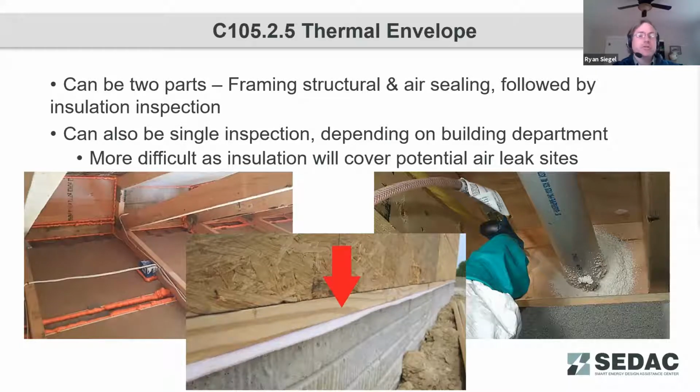that is one opportunity you may have, if you choose to do a blower door test: to do this as early as you can, just to do that verification of the envelope. We go through and verify all kinds of other systems in our buildings, from the fire alarm system to the sprinkler system, many different systems. We verify performance. So doing a blower door or pressure test to verify your envelope performance can be very effective.